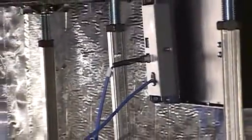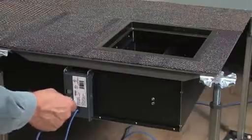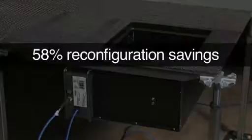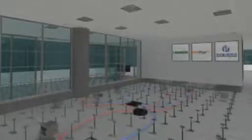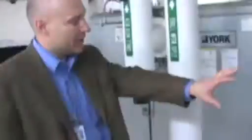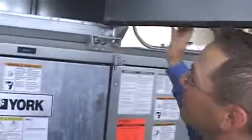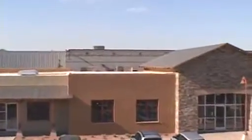Thermostatically controlled floor-mounted diffusers are daisy-chained with simple plug-and-play wiring connectors, so reconfigurations are much less complex than with ducted systems. It's estimated there can be savings of 58% over ducted reconfigurations. Furthermore, to add or change one HVAC zone, we've seen savings in the 22% range. The simplicity of these systems makes them easy to understand and maintain by building maintenance people. In fact, the chillers and rooftop equipment used are nearly the same as ducted systems.